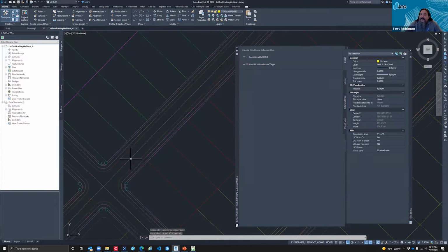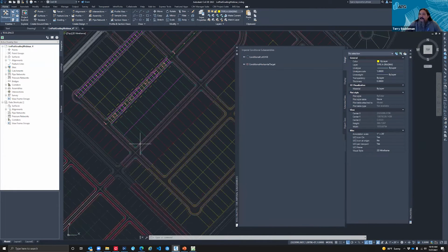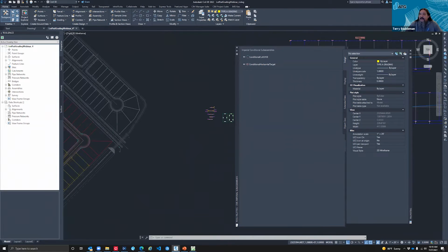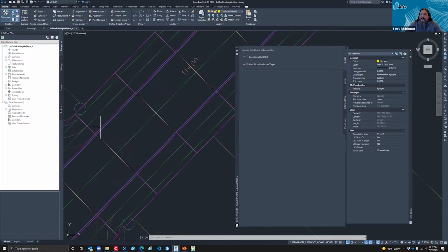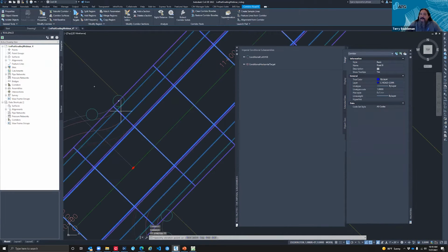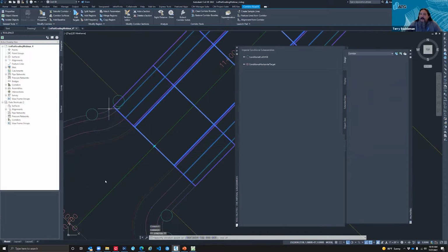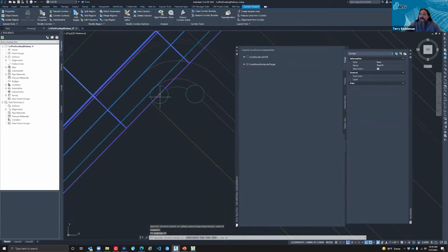So we have line work here in our CAD file. Basically, we have curb and gutter, we have a buffer area, we have a sidewalk, and we have our right-of-way line. Most of the times when we're grading roadways for sites, for residential sites, we'll grade up to the right-of-way. And so our assembly matches our road cross-section. And so with that, it's gone through and lines up pretty well with our curb and gutter and our sidewalk. So I'm just going to take our corridor and tie it, bring it up to this, our curb return here. And bring this one back to this curb return here.